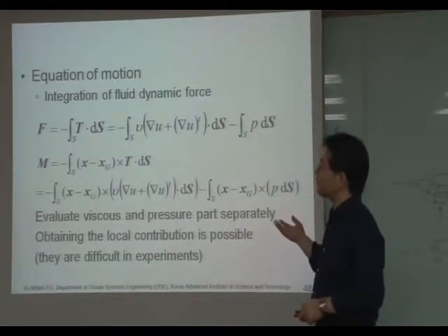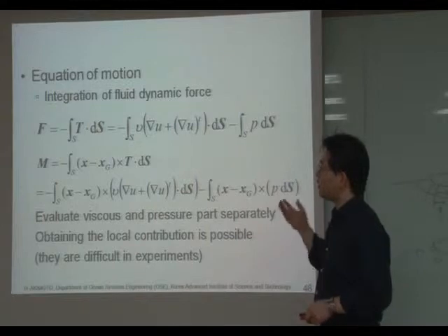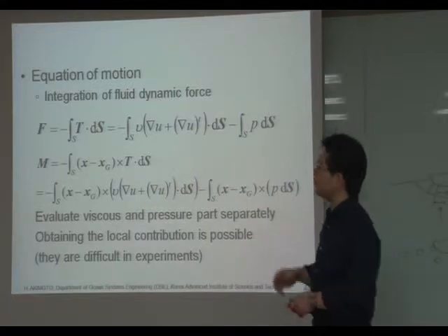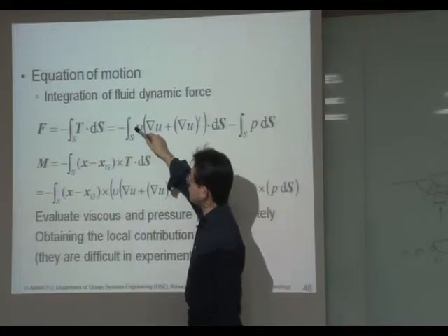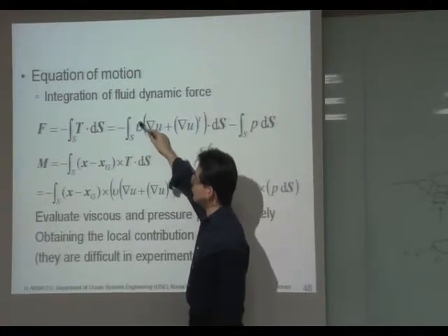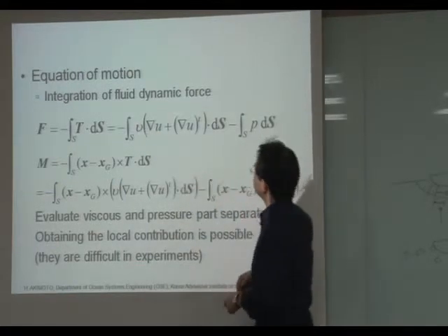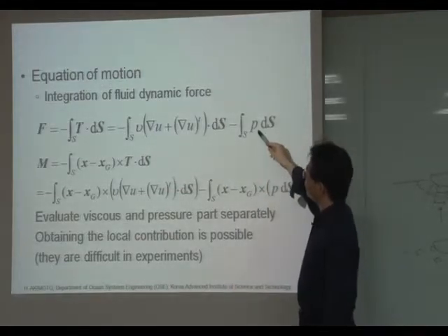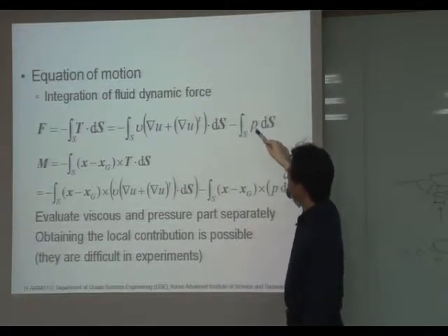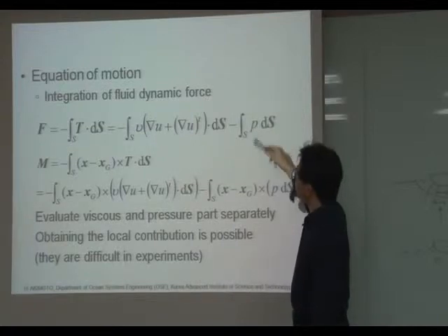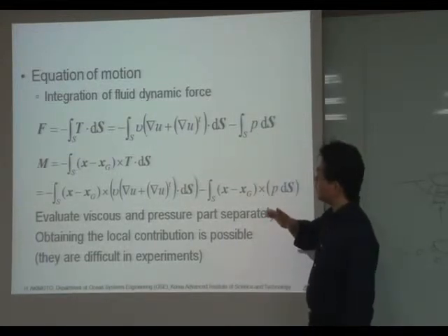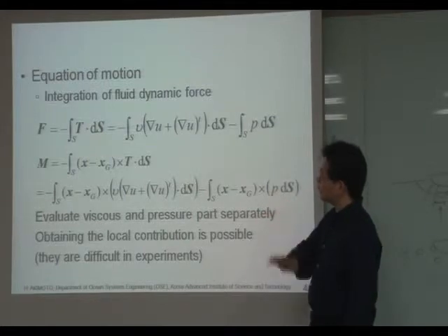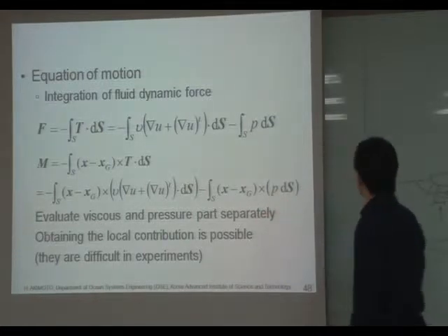If it is a high Reynolds number simulation, the turbulence model, the turbulence viscosity, will be inside this factor. And it has a pressure part. It is the force of pushing pressure on the hull surface.